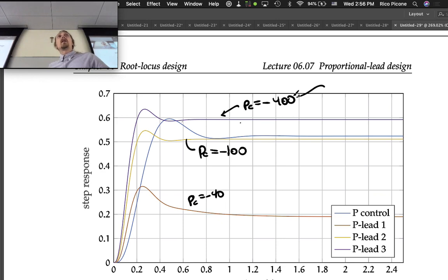But we're also interested to know, okay, if you only have 300 newtons of force that you can apply max, anytime there's a step change in our command, we wouldn't want to be exceeding that. It's called saturating your actuator.